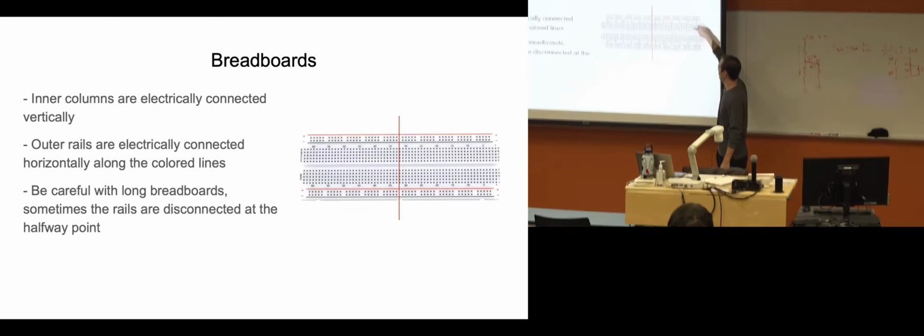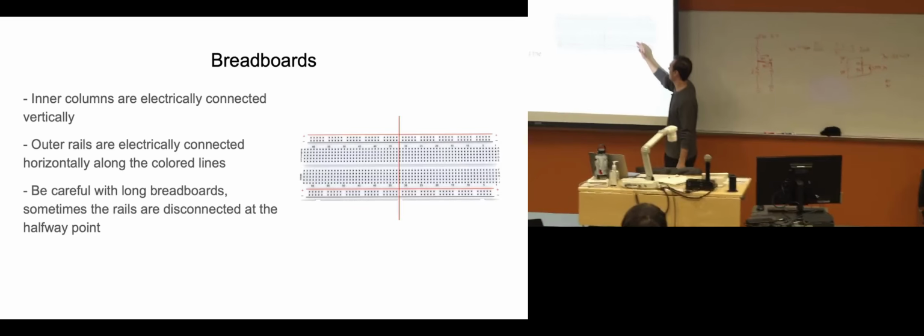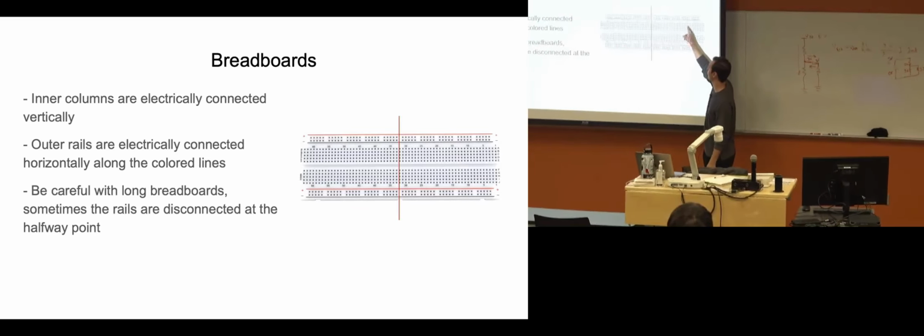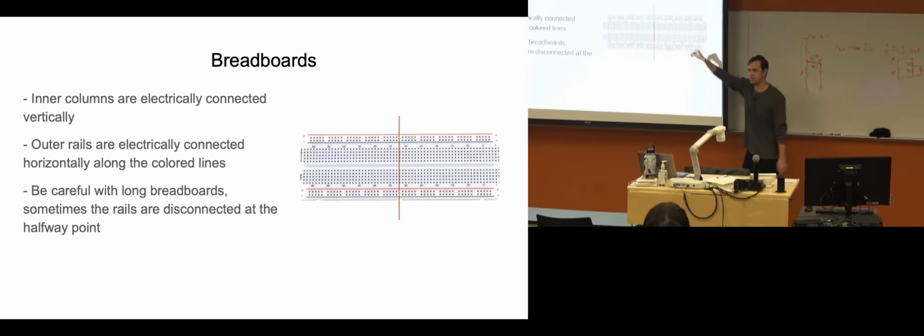I see a lot of people put a resistor from here to here in the same row, and that's essentially shorting the two of them, which is probably not what you want, right? So if you want it to move from one spot to the other, you'll have to go horizontally across this. Does that make sense? The inner workings?